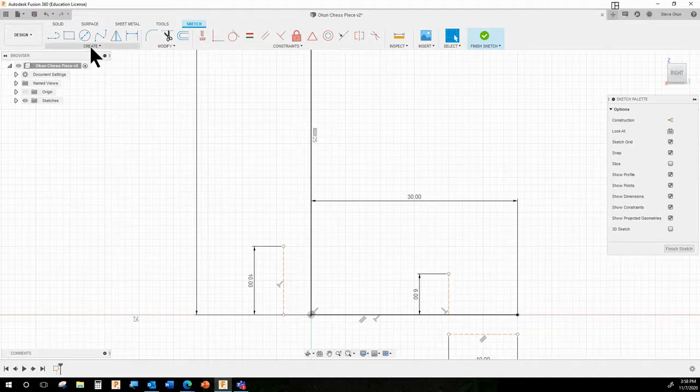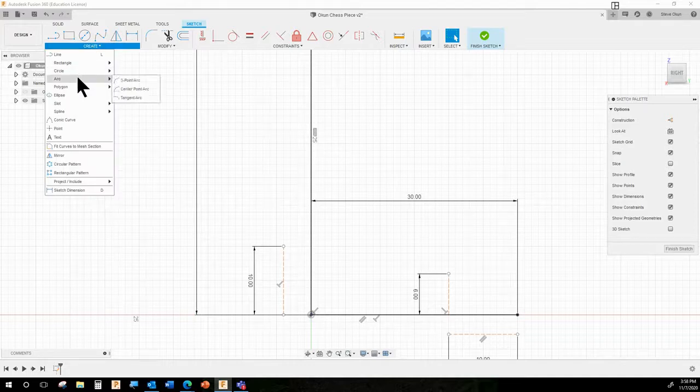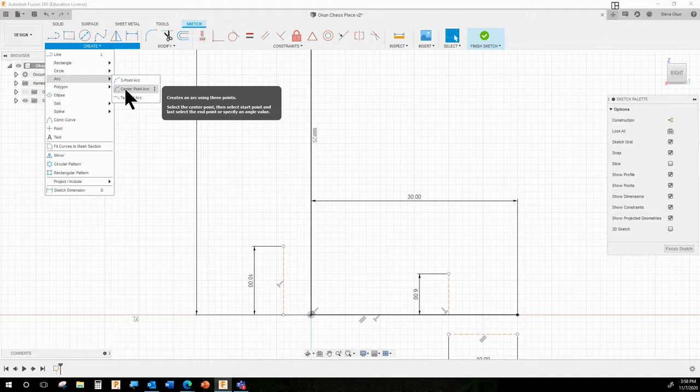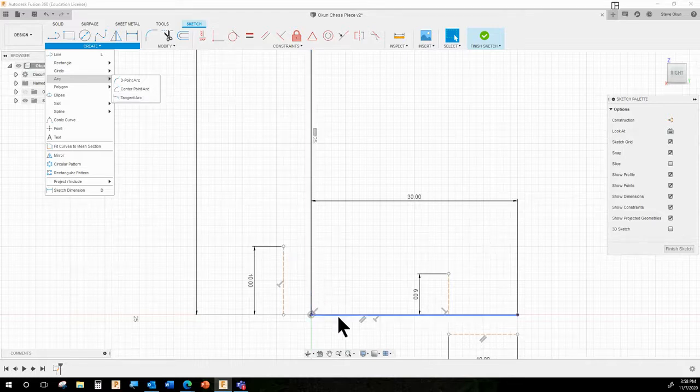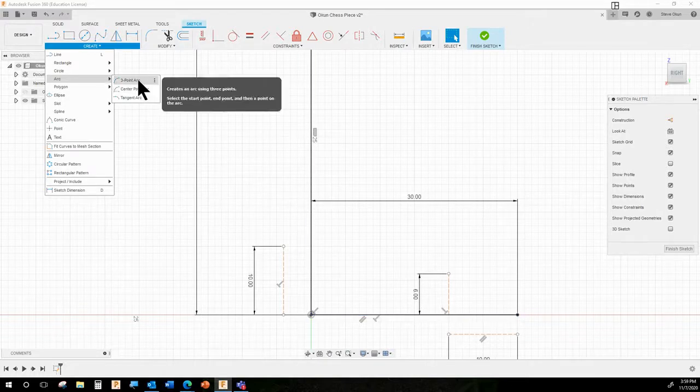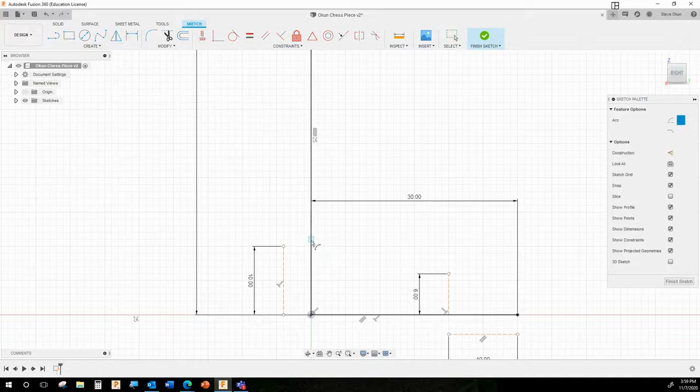Okay. So that gives me a clue as to which kind of arc I want to use. They didn't give me a center point. That's another possibility, and you'll get to use that eventually. They didn't tell me it was tangent to some corner, like here. If I was making an arc that was tangent to this 90-degree angle, I might use that. They've given me 3 points, so it's a good clue that I want a 3-point arc. So I'm going to choose that.